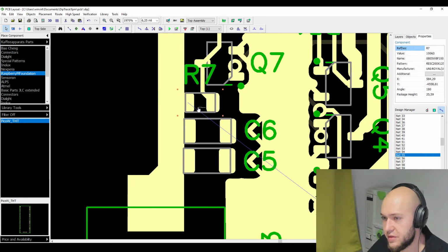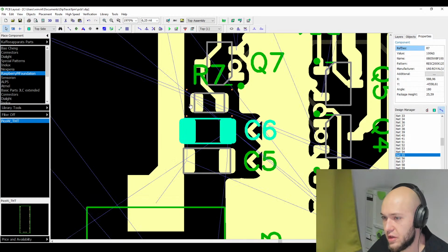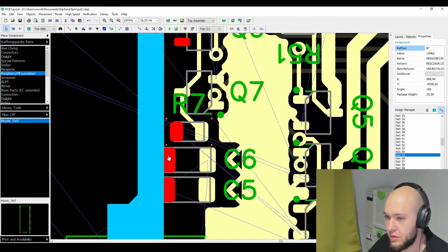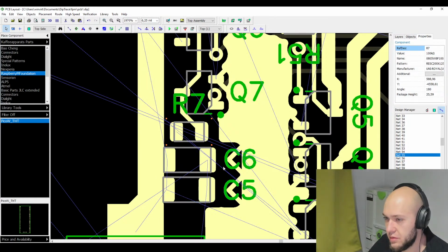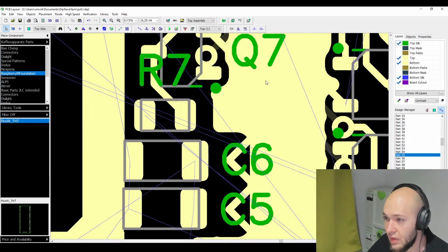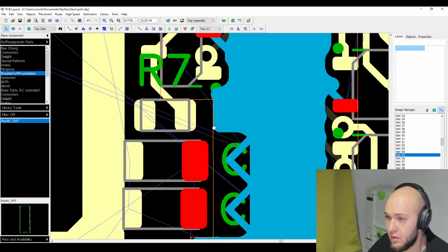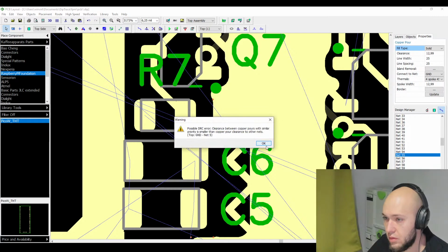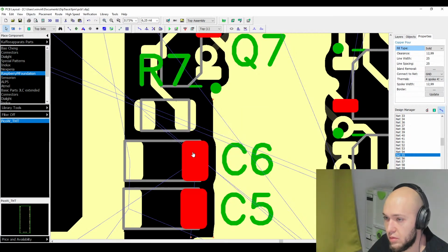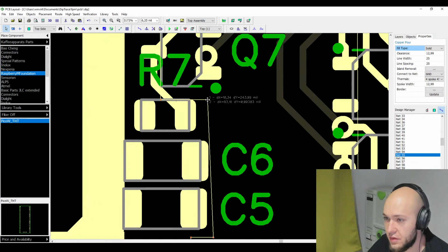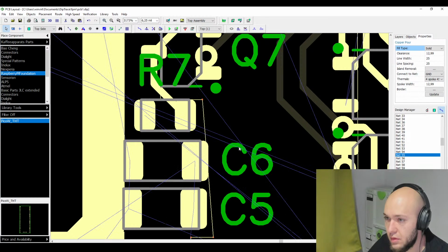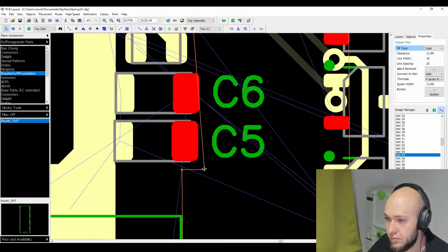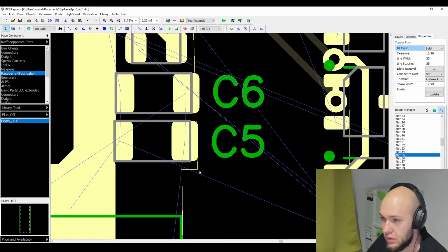We'll immerse the contacts, which are high power, directly into the trace. So these two conductors. We will update our layout. Okay, now they're not immersed enough. Let's immerse them further. Let's remove that point. We don't need this.